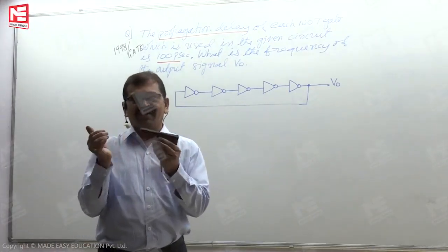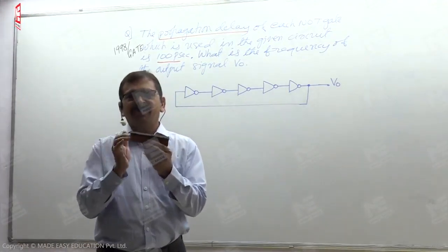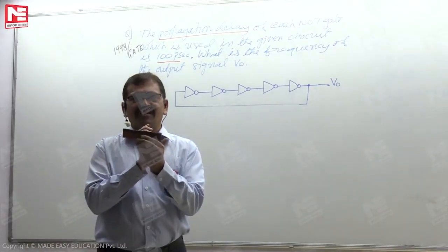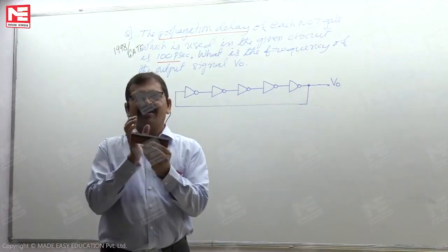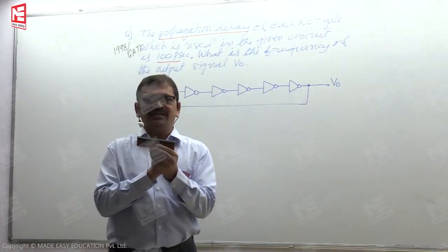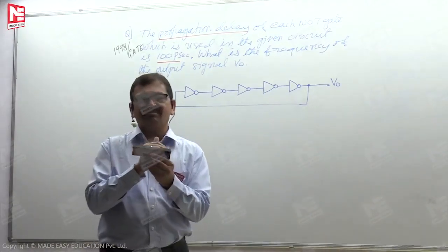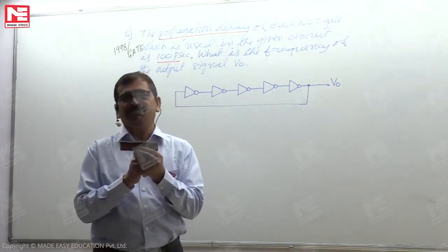Alternatively, after applying the input, a certain amount of time delay is involved before reading the output. Instantaneously we are not reading the output; we need to wait a certain time. That time is the propagation delay.